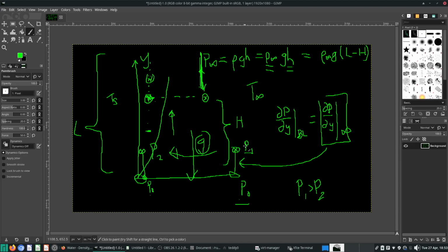So when fluid flows from the free stream region to the P2 region, what happens? After a while, you should expect P2 to equal P1 once everything equilibrates. You give it some time to settle the flow patterns and the natural convection. We should find that P1 is equal to P2, hydrostatically. Why? Because some of the P1 pressure is being converted into kinetic energy so that it can push the fluid from the free stream into the boundary layer. That's one way you can think about it.